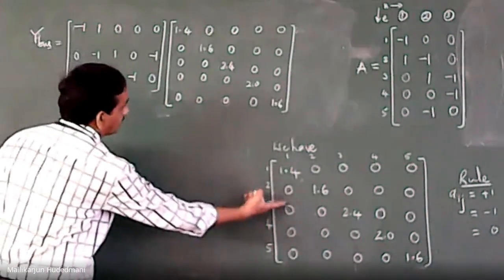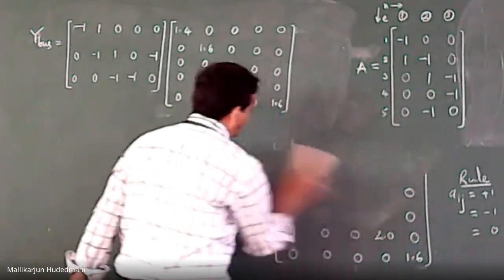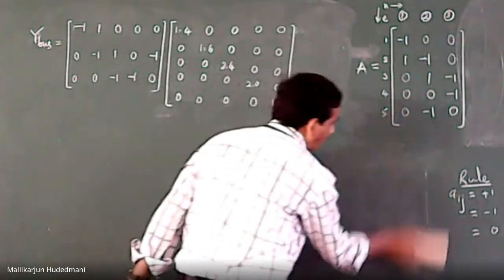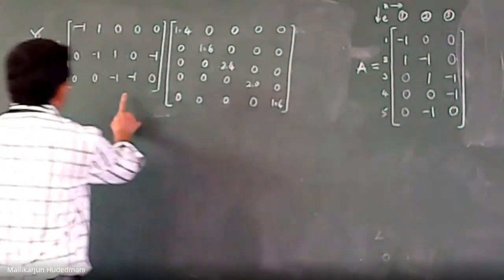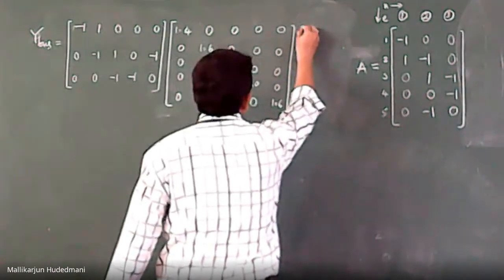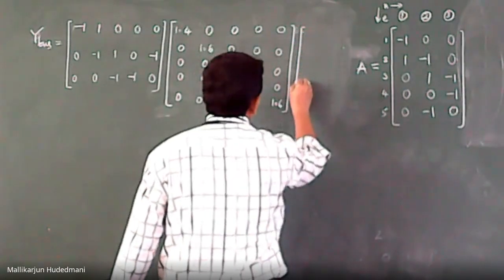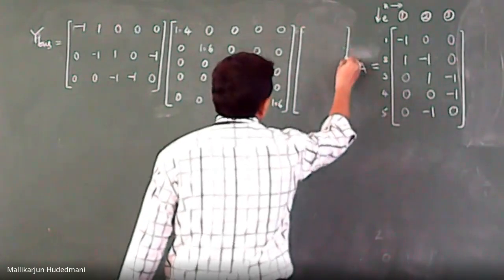I took this matrix over here. Then I will delete this also. I don't require this. I want space for my optimal workout. Into A I have to do. A transpose into Y into A. What is A matrix for me? A matrix is a matrix of incidence of elements with the particular buses.